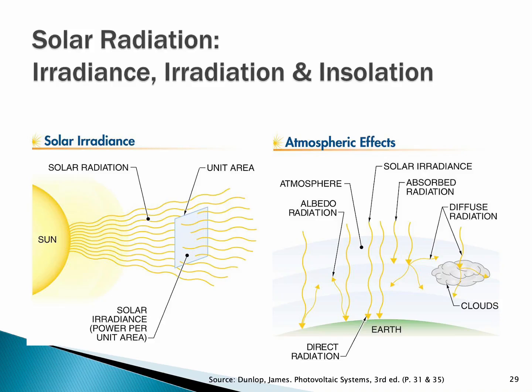And we have a white roof surface, and this fall I was absolutely flabbergasted when we put the irradiance meter on the array at the same angle as the array, and the array was seeing 1,200 and some watts per meter squared. We had this additional 200 and some watts just from the reflective surface of the white roof. So we can enhance the performance of a system by landscaping or roofscaping.